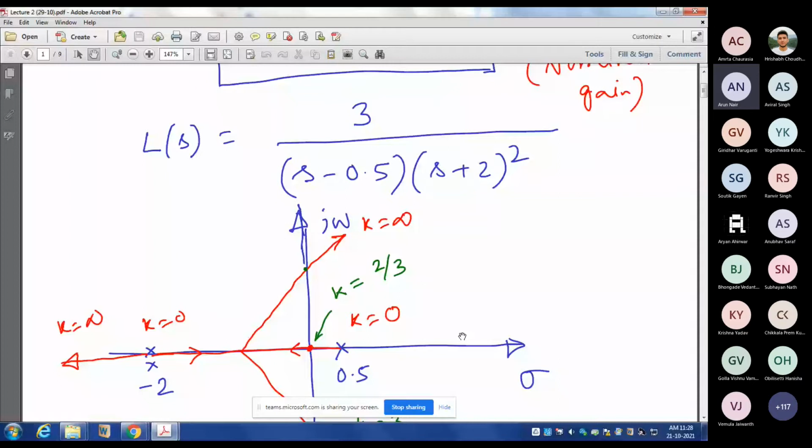Yeah, RH criteria you have to use to determine the imaginary axis crossing. You are saying, right? Yes, sir, for root locus also we ultimately have to use RH. So if only by RH you can ultimately find the range, then I think it is better. Yeah, ultimately we are dependent on Routh-Hurwitz criteria to determine the imaginary axis crossing. Correct. Okay, so this is about root locus.